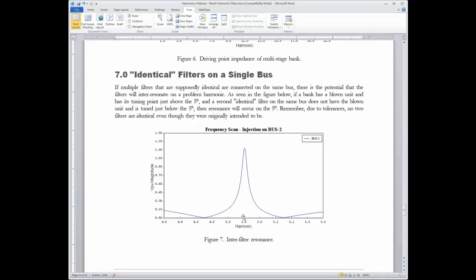The other thing that you can see and discern if you run a few simulations is it causes a resonant condition between the two filters, and their RMS amps double or quadruple. And this is exactly what we saw. I saw a cast in concrete current limiting reactor, which was the reactor for the filter, basically it was almost red hot. It was really cooking.